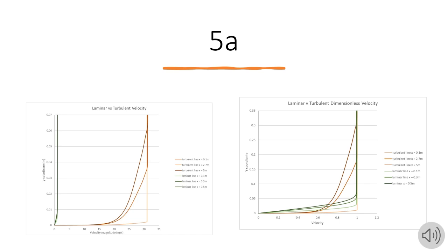For both turbulent and laminar cases, we can see that the velocity is zero at the surface of the plate. This is caused by the no-slip condition, which explains that a fluid is stationary at the face of a surface. This stationary layer of fluid produces a friction force against layers above it. At points further from the plate, the effects of this friction force become less pronounced and eventually it disappears as the free stream is reached.